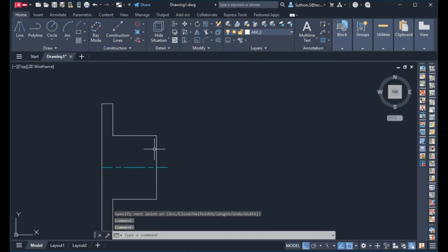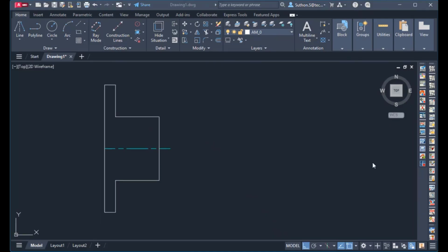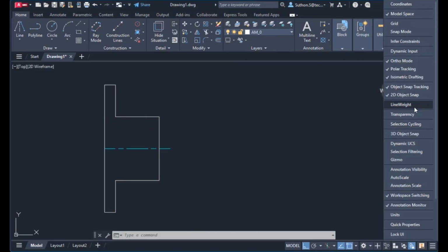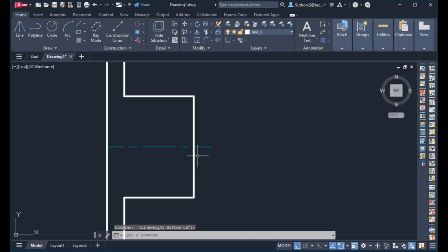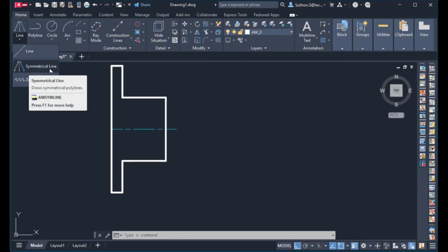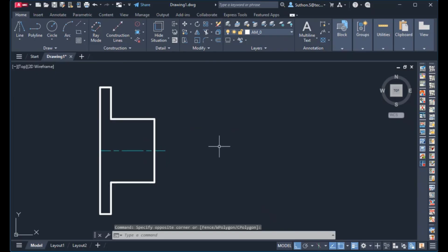And you consider the line weight, right? You think, do I have to set line weight again? No. This one knows, so you can check the line weight. You see, the working line is still thicker than the center line. The system knows that. So you can create all these things within just one command. That quite saves your time and money and reduces errors, because line weight is an error.